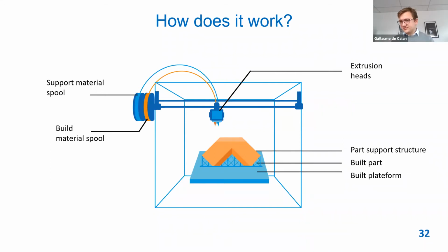You push it through an extrusion head, which will melt the binder, actually. You don't melt the powder, of course, but you melt the binder and you deposit it, and by cooling down, it solidifies. So it's really FDM, FFF of parts, except that the filament is a highly loaded filament with a lot of metal in it.